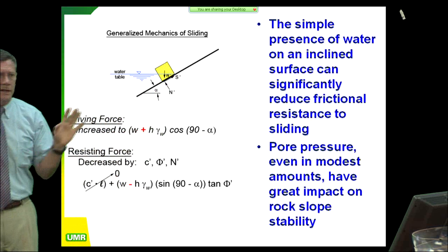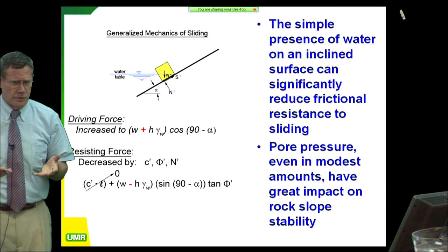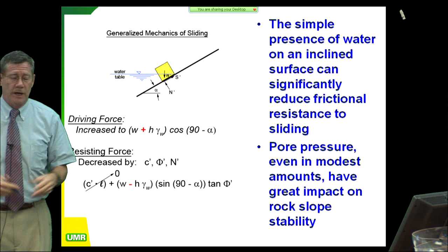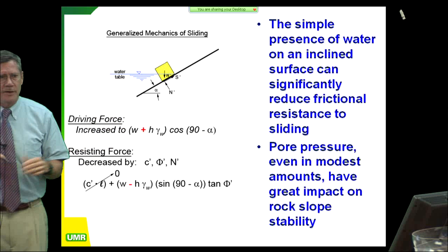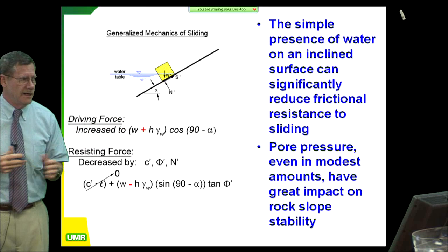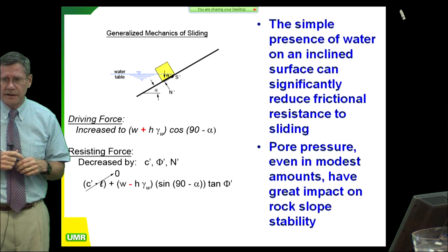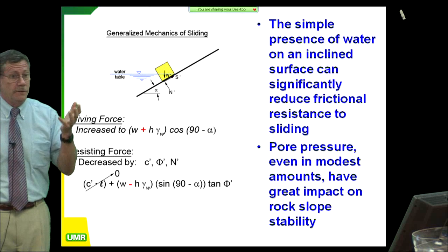And that's what every agency recognizes, and they all say the same thing. Do not fill the lake more than 12 inches a day. Do not drain the lake at more than 12 inches a day. Well, they forget to tell God. And that's what happened with Teton Dam. Teton Dam filled at 36 inches a day. And what could they do about it? Nothing. And it failed on them on the first full filling.